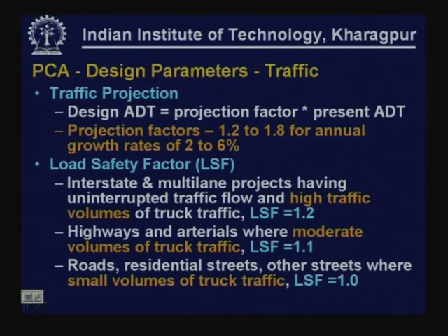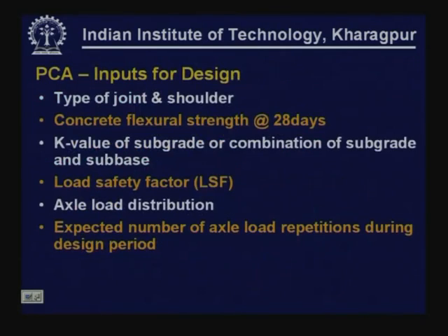PCA also recommends usage of load safety factors, LSF, as we have done in the case of IRC 58 also. For different types of facilities, different load safety factors are given. As you can see here, for high traffic volume roads, load safety factor of 1.2. For moderate volumes of truck traffic, load safety factor of 1.1. For residential streets and other streets where small volumes of truck traffic is there, load safety factor of 1 can be used. These are similar to the values that were adopted in the case of IRC 58.